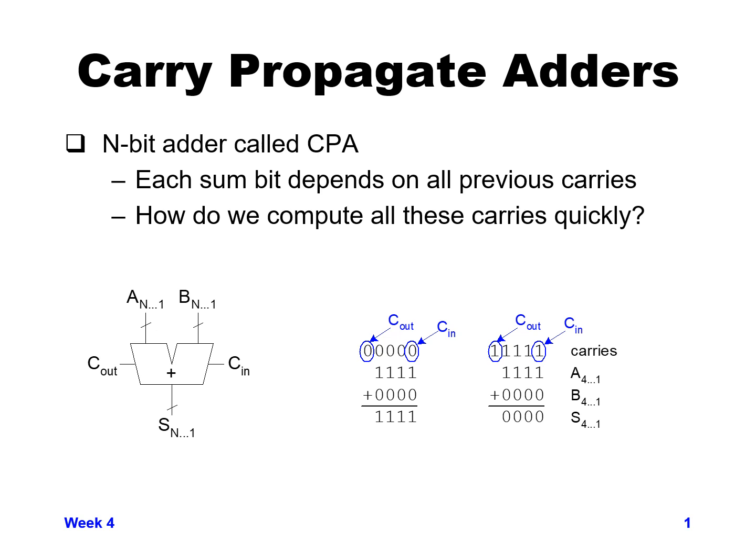With normal addition, each sum bit depends on all of the previous carries. Bit 2 depends on the carry coming from bit 1. Bit 3 depends on the carry coming from bit 2, which depends on the carry coming from bit 1. So in effect, if we have an n-bit adder, we have to compute n carries, and those need to be done sequentially, or at least one potential consequence is doing them sequentially.